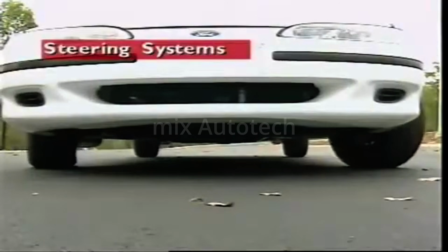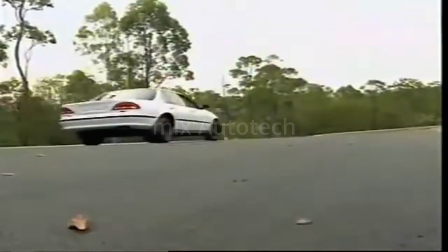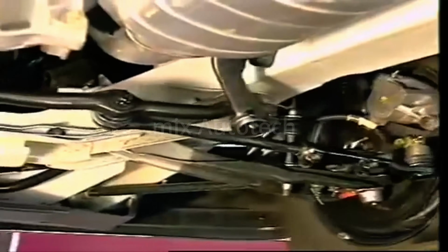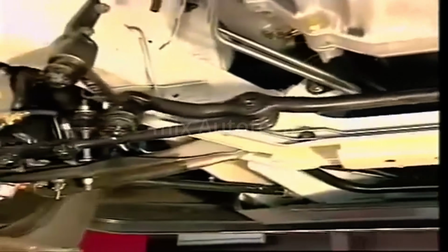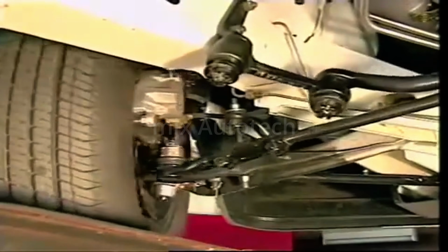This section examines steering systems. The direction of motion of a motor vehicle is controlled by a steering system. A basic steering system has three main parts: a steering box connected to the steering wheel, the linkage connecting the steering box to the wheel assemblies at the front wheels, and front suspension parts to let the wheel assemblies pivot.